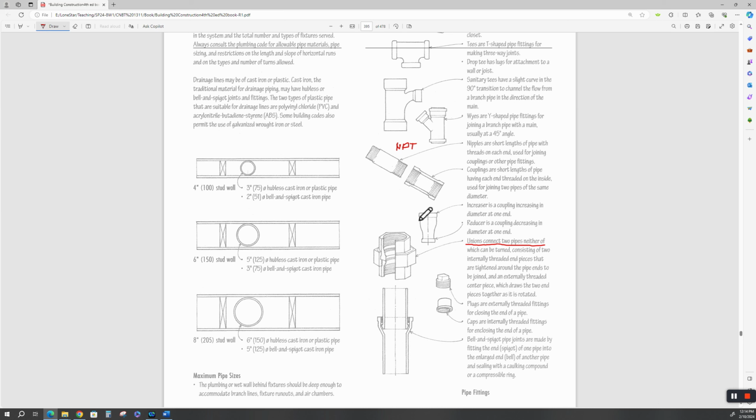Let's see. For gravity sewer patching, you can use an elastomeric coupling that has pipe clamps on both sides, and you can clamp two square ends of sewer pipe together. These are plugs. They'll plug the end of a pipe. Let's say you've got a deadhead reducer and you're not going to put anything on it. You can put a pipe plug in that one.